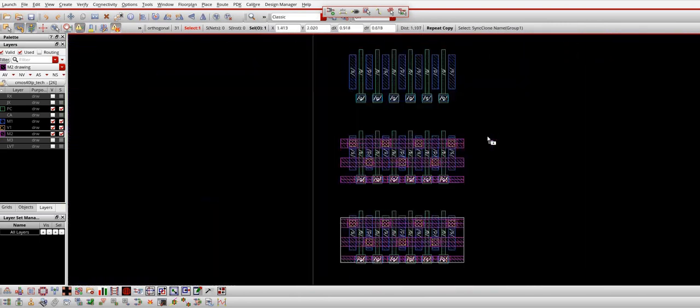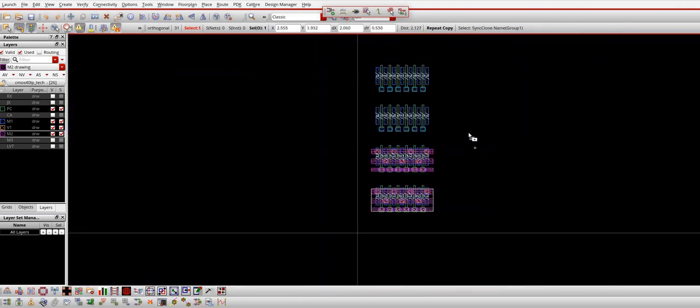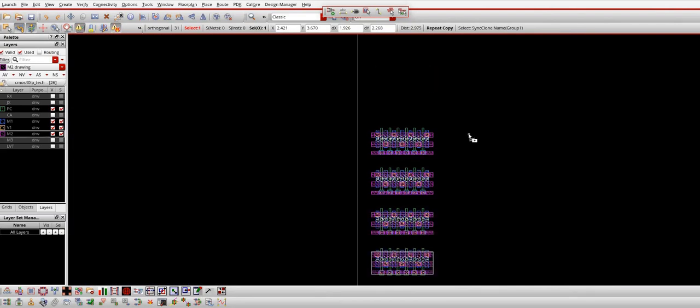I'm still in the copy mode here. Now I will just press dot. Again a dot, again a dot. The more dots I press, the more synchronous groups get copied. So here I've used recursive copy with the synchronous copy option.